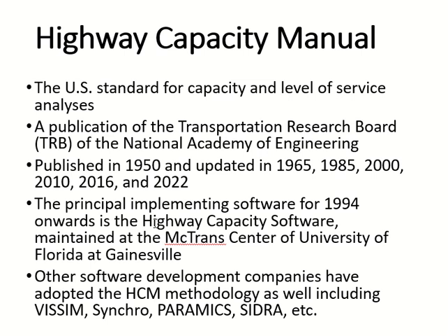And then later on, with the popularity of the manual, when the procedures were adopted by other countries, other software companies adopted the calculations. So they inserted the level of service calculations and procedures from the Highway Capacity Manual into their software. For example, Vissim, which is a German software, has the level of service calculations and capacity and everything which is coming from the Highway Capacity Manual.